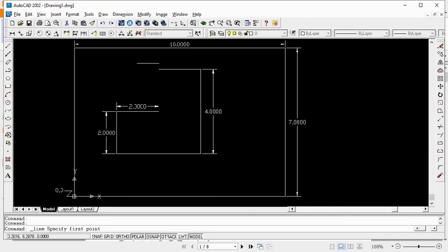So just tracing through this, I'm going to start from 2, 2. That is my first point. The next point is at how far on X? Nothing. I'm not going to have any distance on X, only Y. And then from there, I go to @2,0. This time, I'm going to move 2 on X, and I'm not going to have any distance on Y. Note that is from the previous point. From this point to go here, I'm not having any values of Y, only values of X.